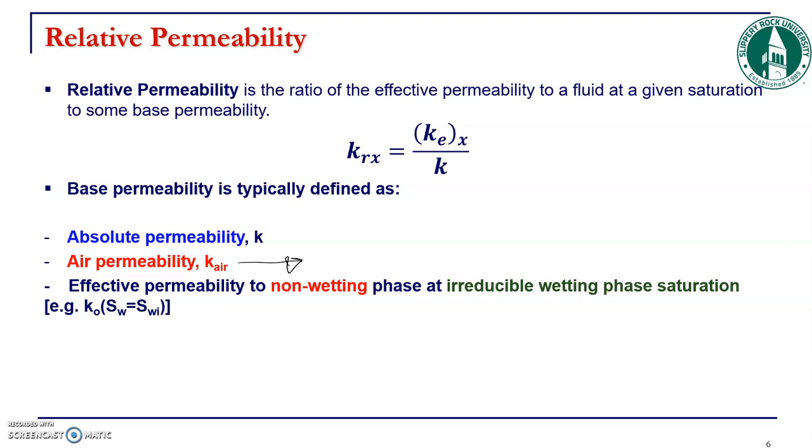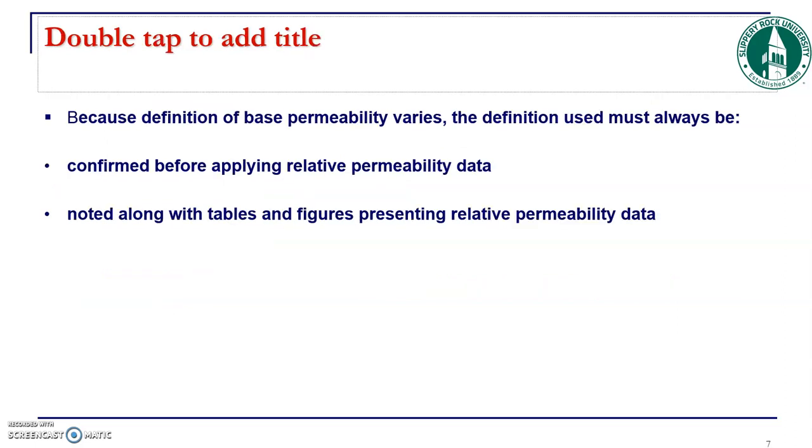Remember, we did the gas permeability using the Klinkenberg effect, and if you measure the air permeability at different mean pressures between the lower and upper point of your sample, you can use that to calculate the absolute permeability using the Klinkenberg effect, right?